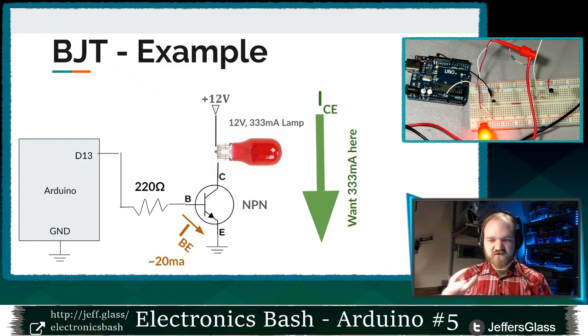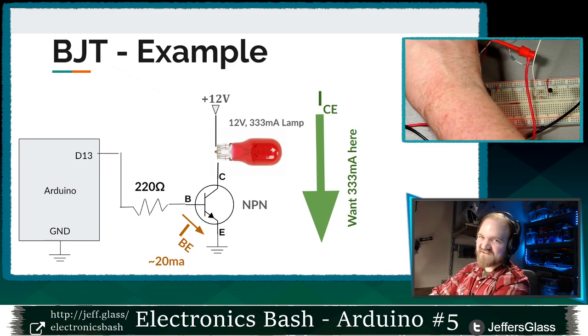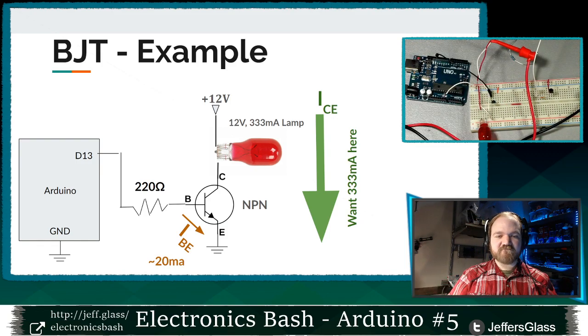One thing about this circuit is we're trying to lock this into our head and understand why it is the way it is. Because I kind of just said, this is how we're going to do the circuit, trust me, wire it up, and it works, which is great. Here, I'll unplug this for Palmer's sake. Why is this circuit wired up the way it is? In other words, why is the transistor down on the negative side of the light bulb?